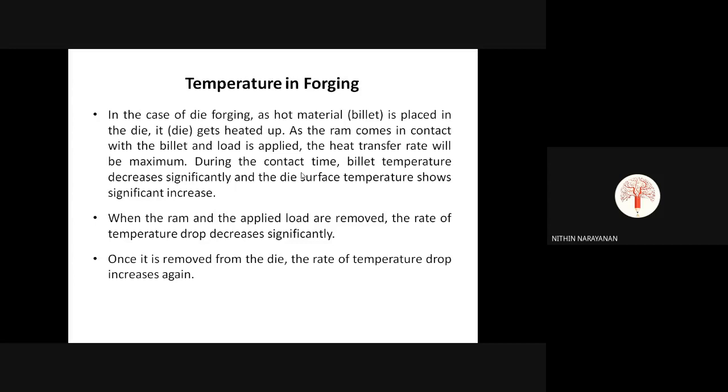So the billet, where plastic deformation is happening, is in contact with the die. So whatever heat is generated in the billet will be transferred to the die because it is in contact with the die. So during this contact time, the billet temperature decreases significantly and the die surface temperature shows significant increase.